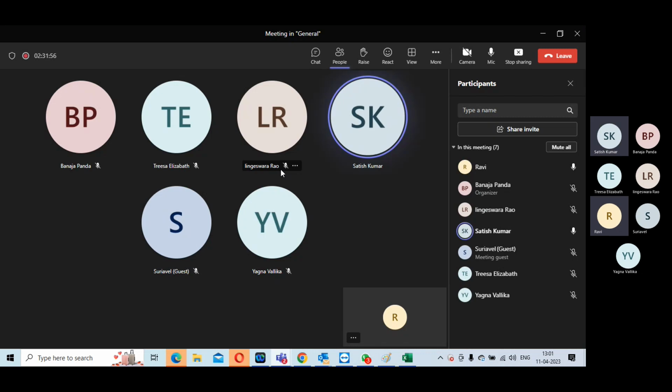If somebody is hurrying you, saying I need feedback on my netlist, I've released it, I have to give feedback, and you have not worked on your floor plan but they need a database, you run a parallel run. Just fire a dummy run for them, if one license is available, but your job for closure should be to get the floor plan clean.